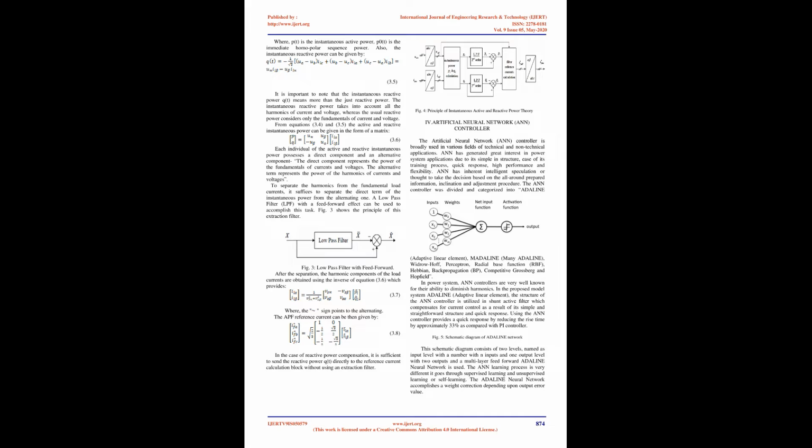the load but 180 degrees out of phase. This principle is applicable to any type of load considered as a harmonic source. In this way, the energy distribution system considers the nonlinear load and the APF as an ideal resistance. The control circuit is operated with a phase lock loop, proportional integral controller and hysteresis controller, which is used to generate the gating pulses for the 4-leg inverter and is carried out at the load side with a nonlinear unbalanced load.